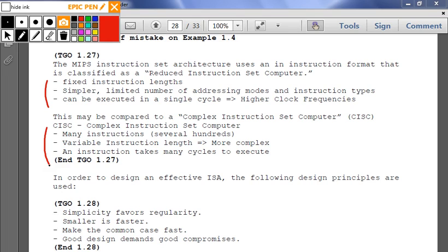If you have a compiler-driven encoding of the microengine where you're using the same instructions a lot, it can be faster. But if I'm taking advantage of the greater hardware, I can get CISC, and eventually we're going to be discussing very large instruction word towards the end of the course. You can get that to actually run faster because you can have multiple instructions going on in the data path simultaneously. So the answer is yes and no.